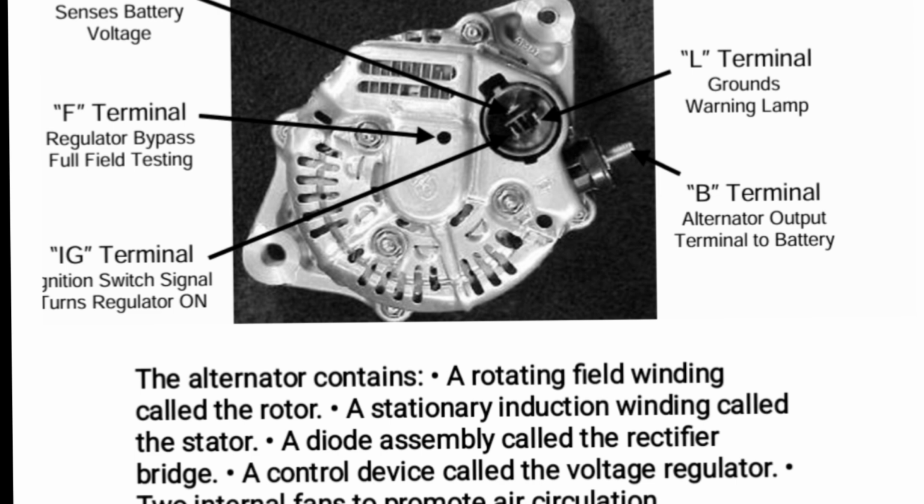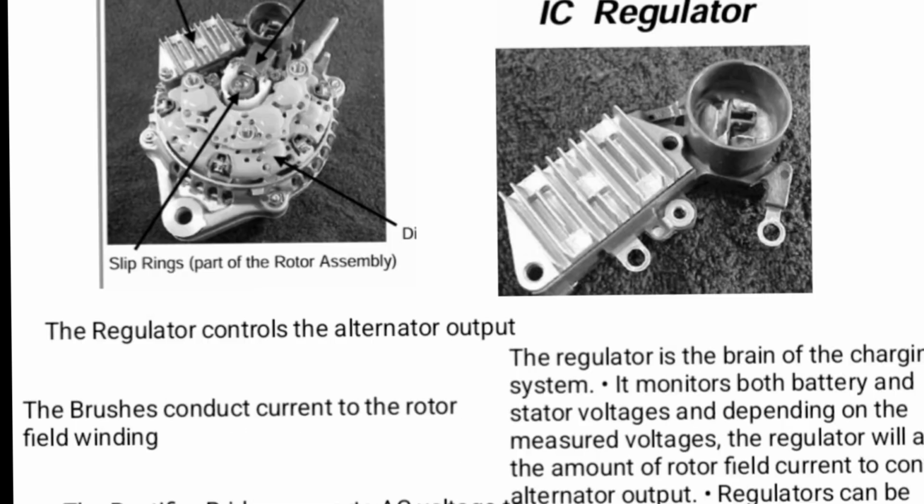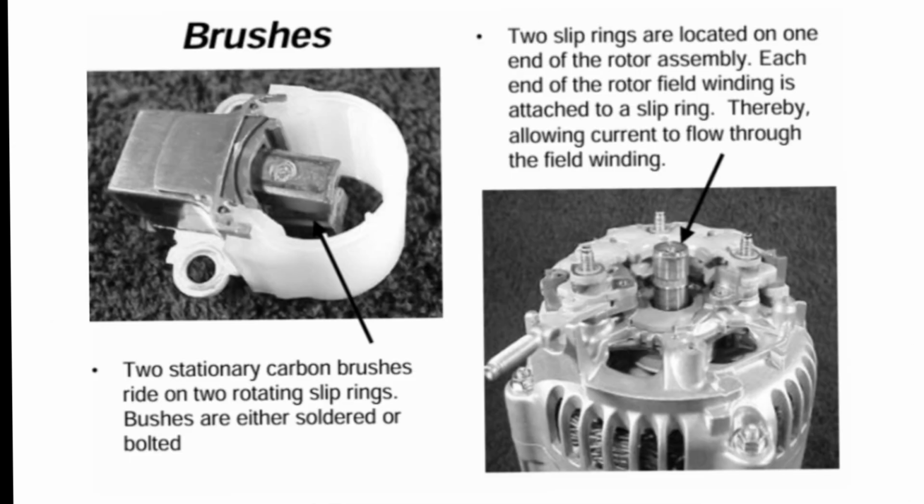Charging voltage test. Start engine and measure battery voltage. Normal reading: around 13.5 V to 14.5 V. Load test. Turn on headlights, blower, AC. Check whether voltage remains stable.